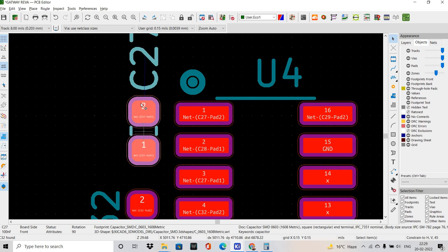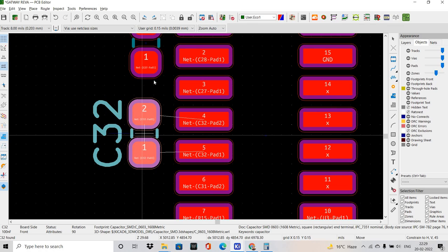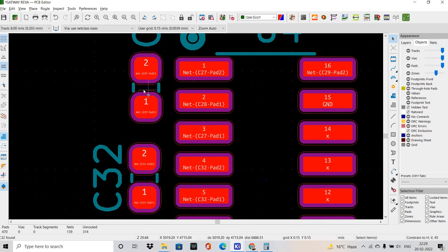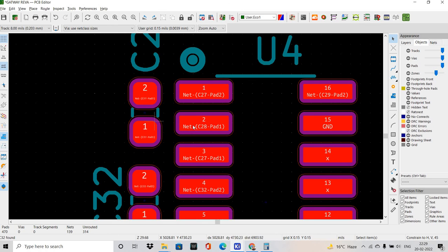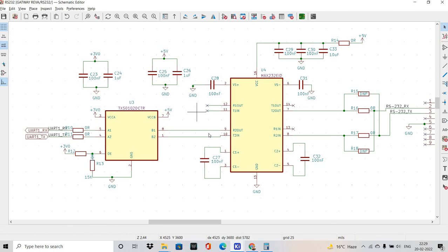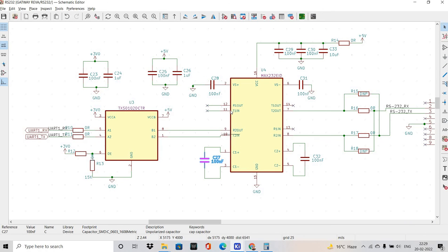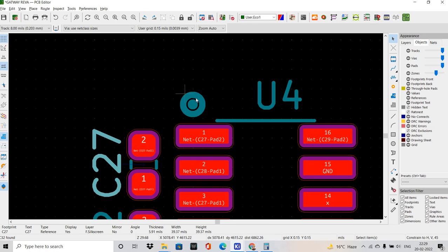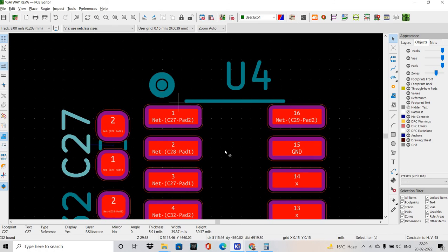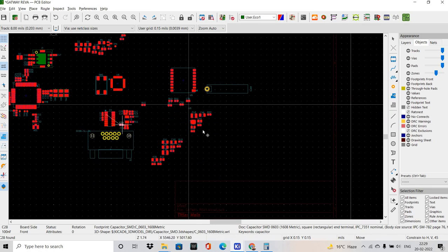Okay, so that I'll have extra space for this capacitor placement. So I'm just doing it for the capacitor. So this one is for pin 1 and 3 and the pin 2 as capacitor again. So pin 2, C28 is here.